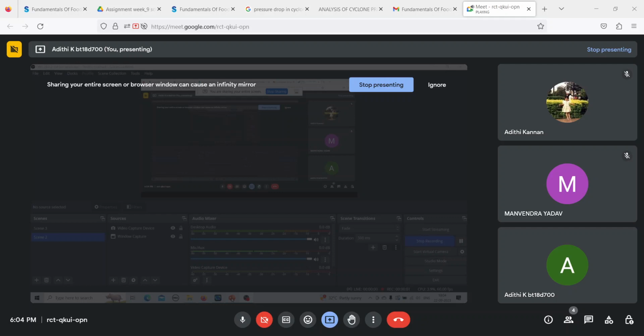So it basically means that smaller the capacity, greater the effectiveness. If you are able to load only a small amount of material, then you won't be overloading the screen, so your separation will also be good. But if you put too much mass of the material onto the screen, then the separation effectiveness will reduce. So it's kind of inversely proportional. Smaller the capacity, greater the effectiveness.